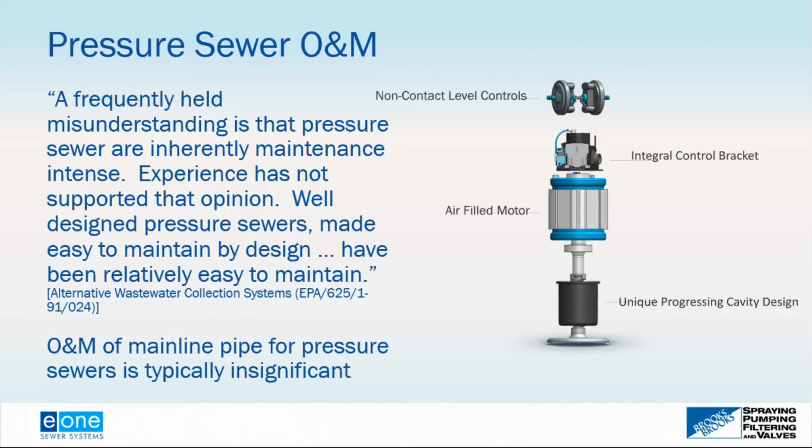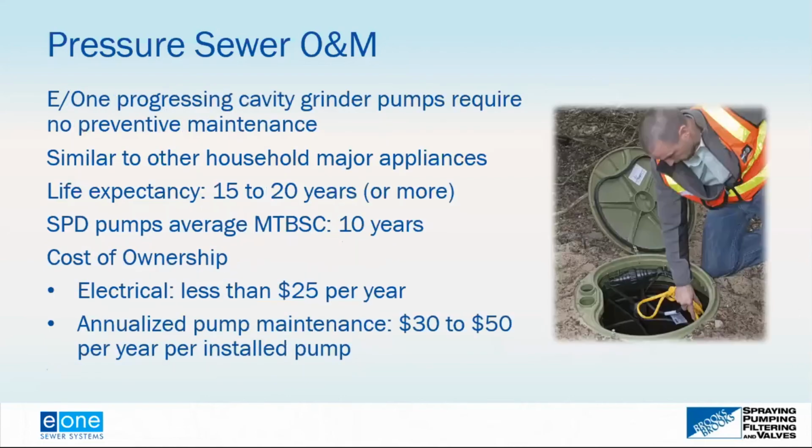So the EPA document actually went through, and I love this quote, but it says, basically, well-designed pressure sewers made easy to maintain by design have been relatively easy to maintain. So if you have a good low pressure sewer collection system with good pumps in there and a proper design, you're not going to have a lot of maintenance. Operation and maintenance of the main line is also very insignificant because you have the pumps themselves that tend to flush any debris or solids that might settle in the system.